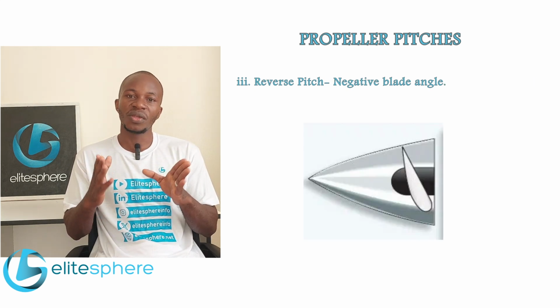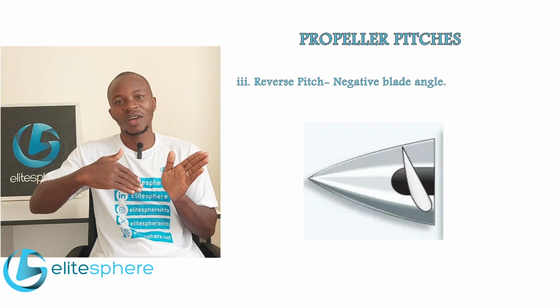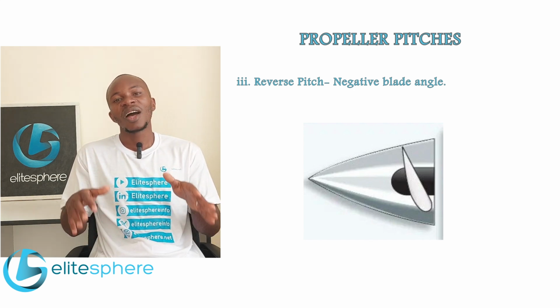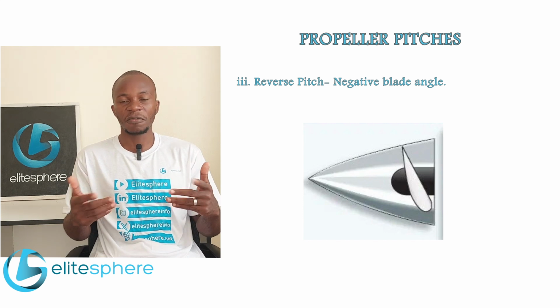During reverse pitch, the blade angle is slightly set at a negative angle, and this assists in stopping or bringing the aircraft to a stop after landing. And the next pitch that we're going to look at is the feather pitch.